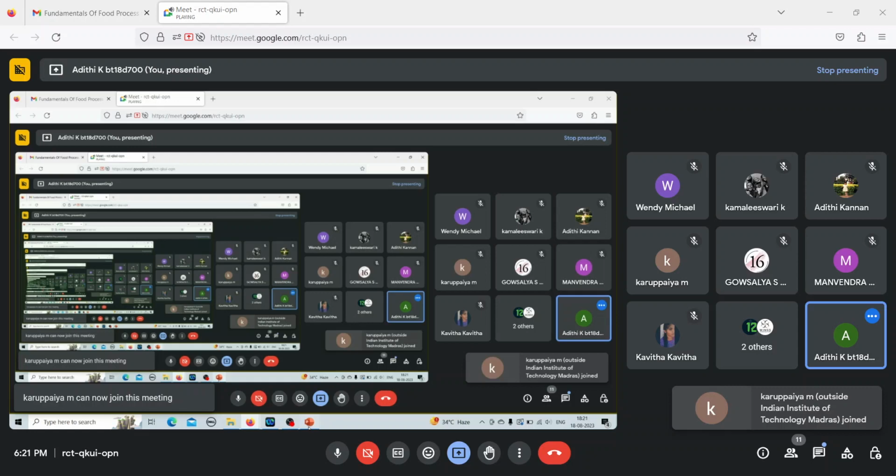And then the specific enthalpy of the saturated vapor at 323 Kelvin is 2250 kilojoule per kg. So we will call the latent heat of vaporization as lambda. And here if you see the saturated vapor at 323 Kelvin, that is this stream. The V stream is coming out at 50 degrees Celsius, which is 323 Kelvin. And at that temperature, the enthalpy is 2250 kilojoule per kg. And then you have the heat capacity of the feed and the product also given here. And you have the overall heat transfer coefficient. So with these in hand, we will figure out how to calculate the heat transfer area required.